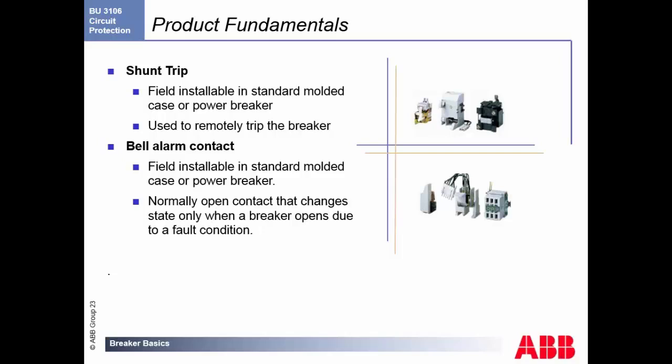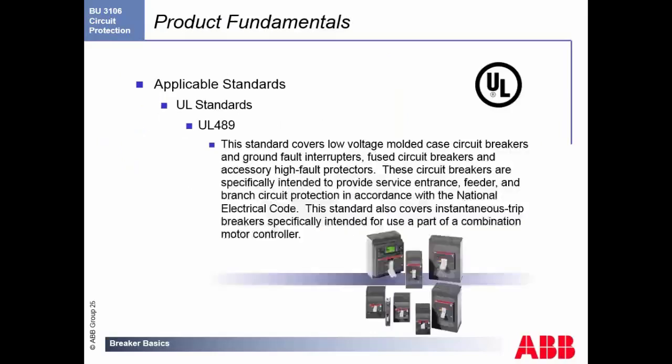We want to make it so that you can remotely tell what the breaker is doing, and we have trip units that actually can tell you why it did what it did. So some of the applications that we have. The UL standards, UL 489, this is the low voltage MCCBs, molded case circuit breakers, and ground fault interrupters. These are for service entrances, feeders, branch circuits.